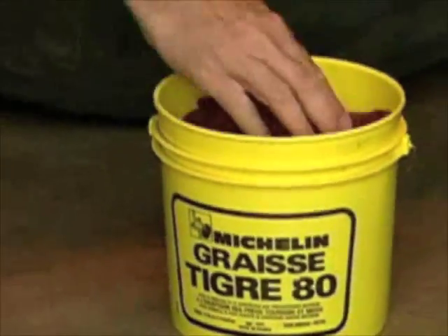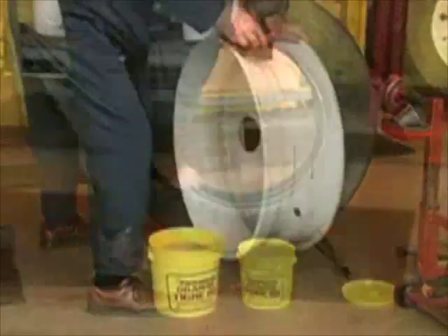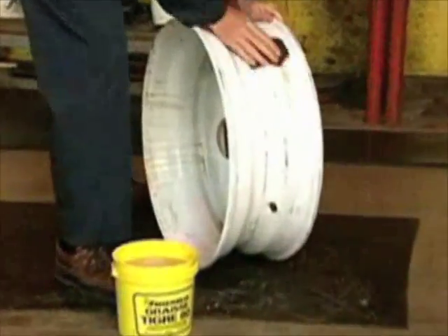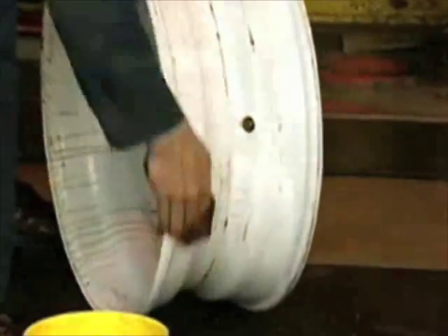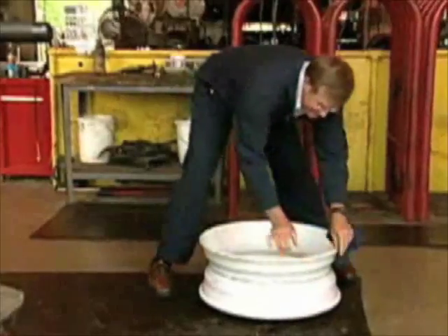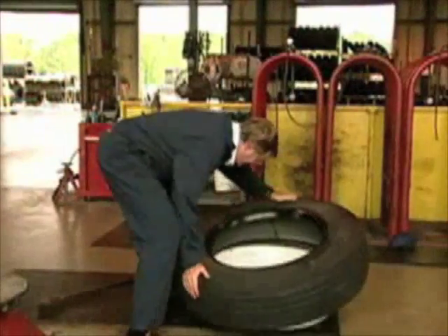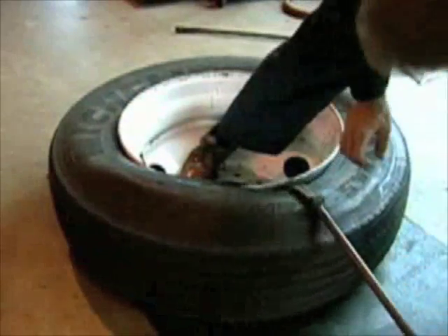A proper lubricant should be applied to all surfaces of the bead area of the tire. When applying lubricant to the rim, lubricate the entire rim surface from flange to flange. Place the wheel or rim assembly on the floor with the short ledge up. Lay the tire over the rim at the valve side and work it on with proper tubeless tire tools, making full use of the drop center well.